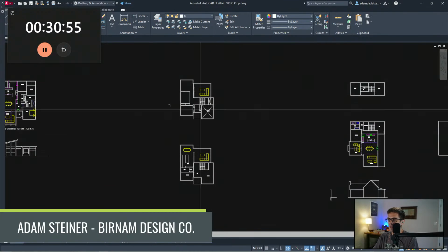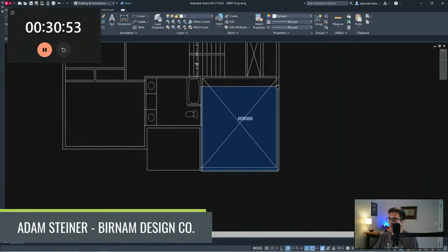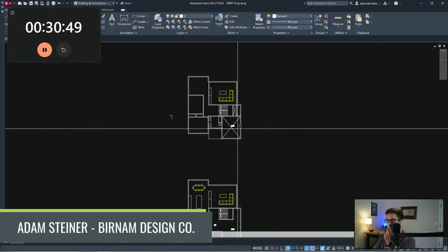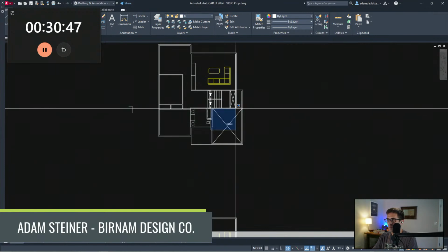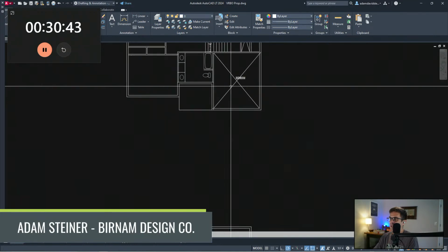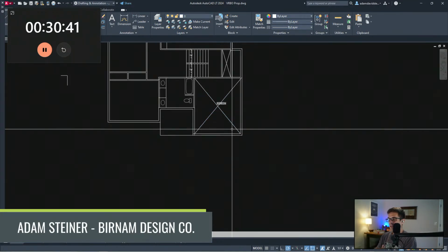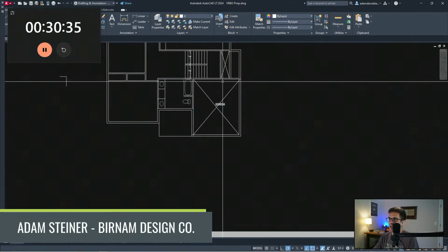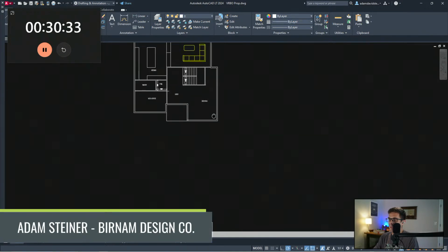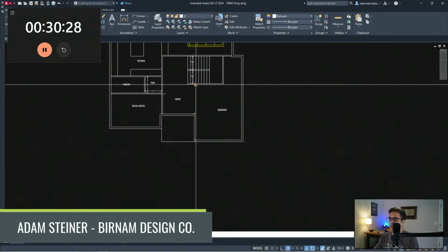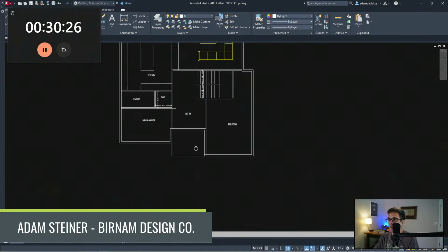Actually, you wouldn't be able to do a full vaulted roof because the main roof would come through here and sit over this bedroom, at least that's what I drew on the front elevation. I guess you could do a girder truss there and just dummy walls out. That would still work to still do a vault if you really wanted the vault.